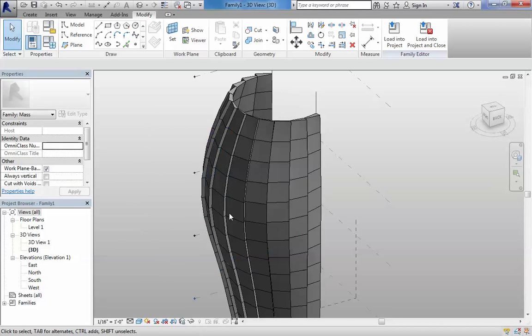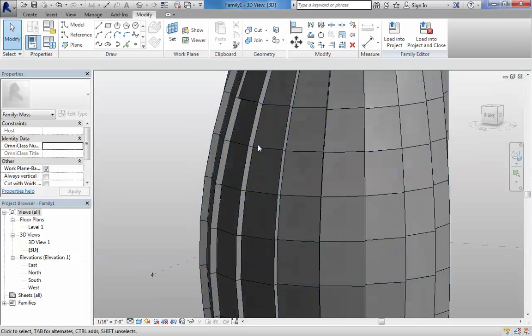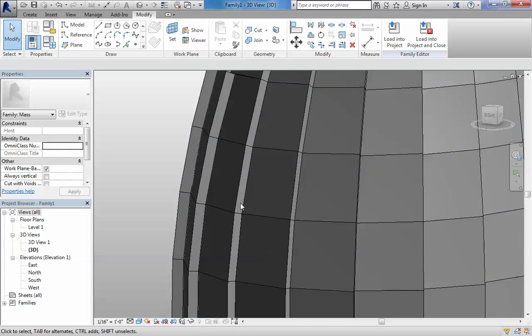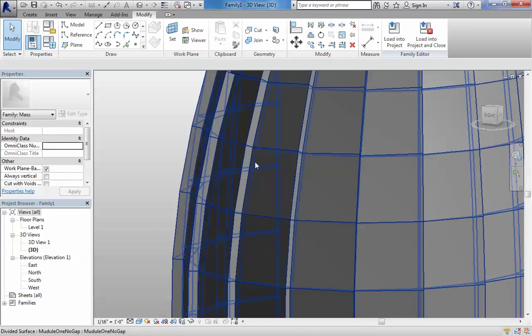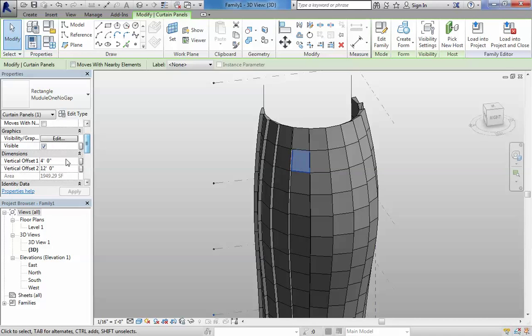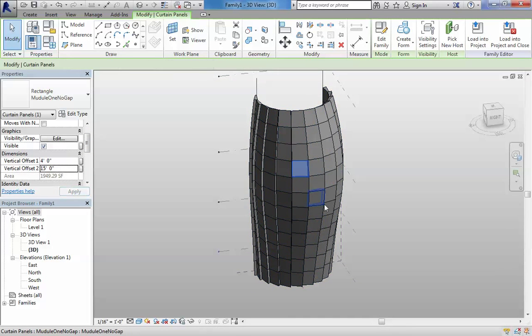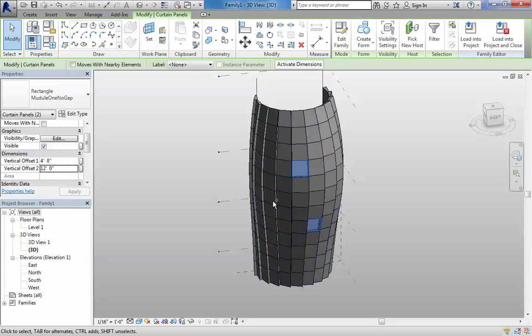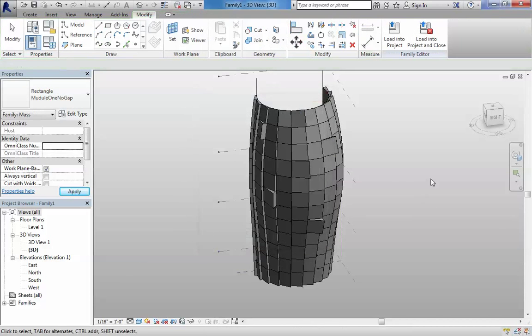There you go. This is obviously vertical. You could have set that the points that they have this variation are going downwards, so it goes like sloping with the curve. Again, you can select individual ones and change some of the parameters, like let's say 15. You can select several of them by pressing Control and changing the parameters here, 25, and then you have the changes.